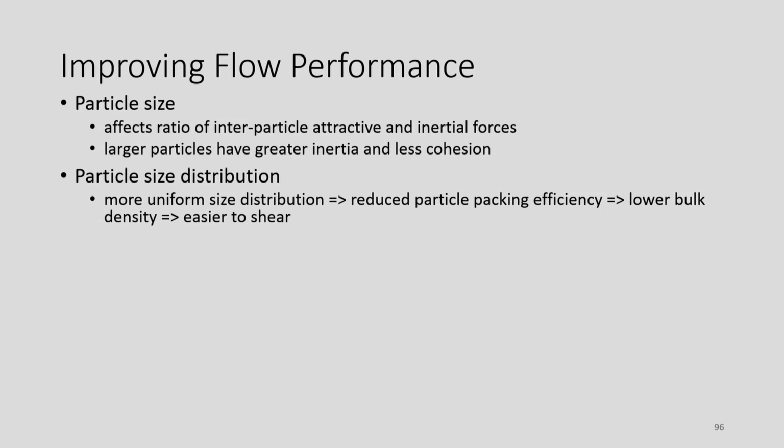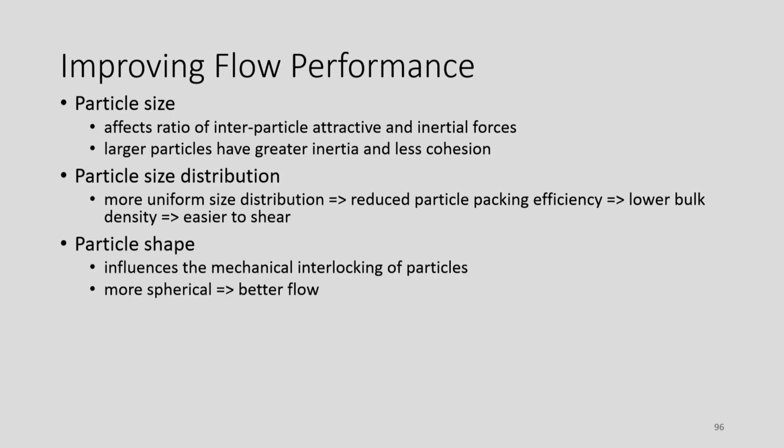If it's highly mixed particles, then the smaller particles will fit into the white space between large particles, and that increases the surface interactive forces, right? Shape also matters: ideally, more spherical particles will have better flow, right? But if it's irregular, there will be more interlocking between the particles.